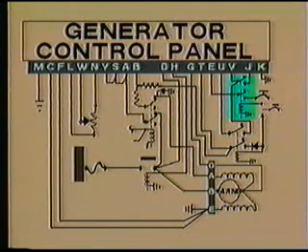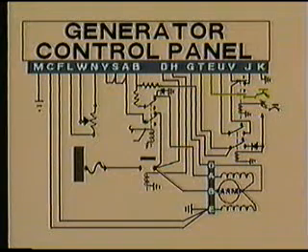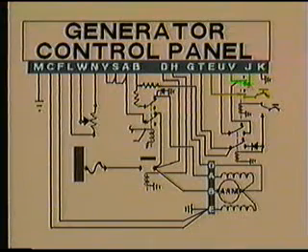The generator on relay also has a dual role. When the generator switch is turned on, the relay engages, closing two sets of contacts. The first set connects a sample of the bus voltage through a circuit breaker to the reverse current and auto line contactor amplifiers inside the control panel. The second set of contacts allows the output of the generator B terminal to be routed into the control panel.